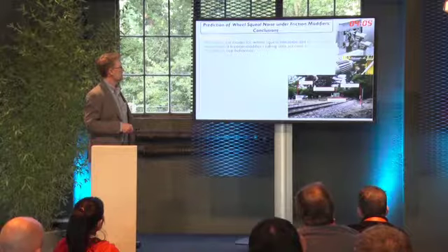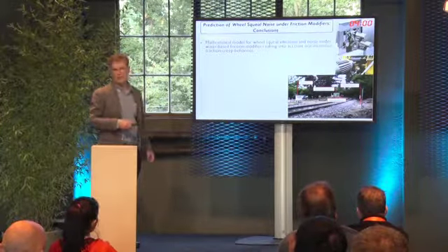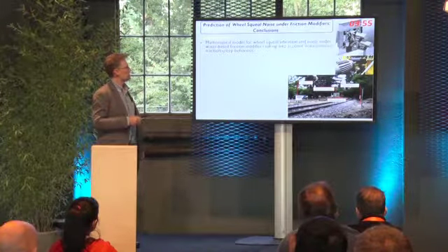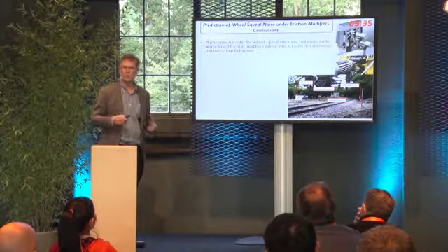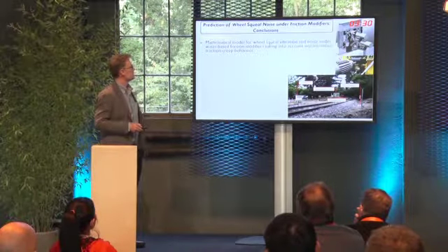So, in conclusion, we've developed a mathematical model for wheel squeal vibration and its noise amplitude under water-based friction modifiers, taking into account an instantaneous traction creep behaviour that we can't measure, at least yet, using existing technology. I should mention the mathematical model is based on the conventional mechanism of squeal, and there's a lot of research on other mechanisms such as mode coupling at the moment.